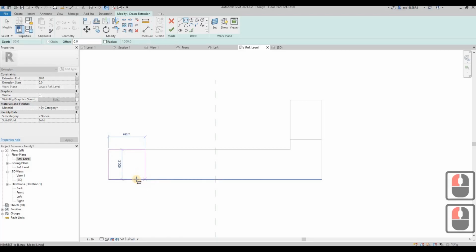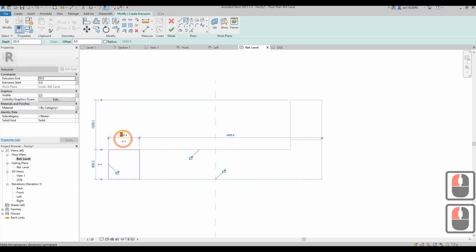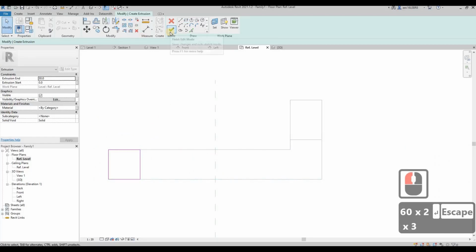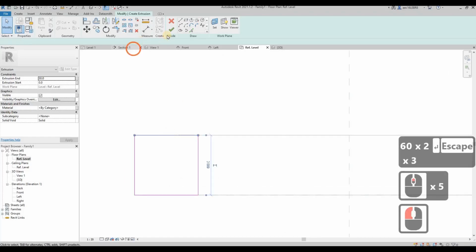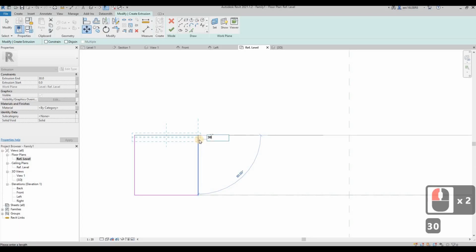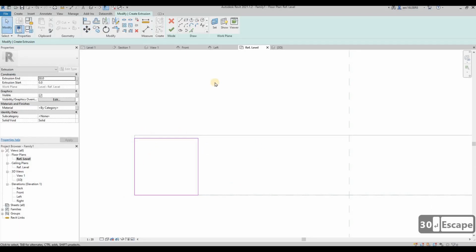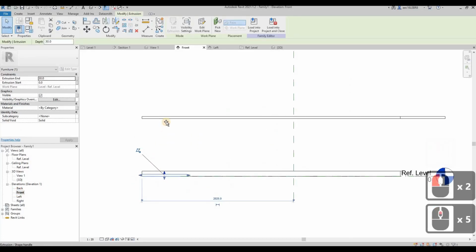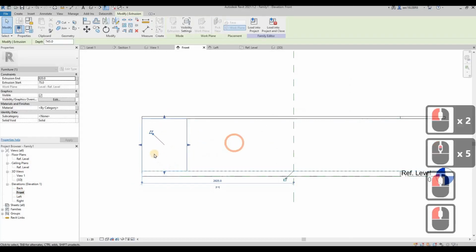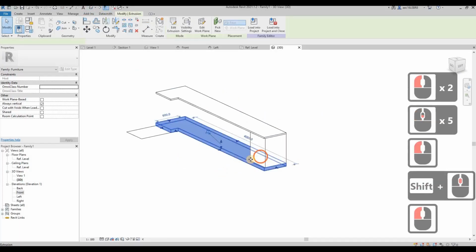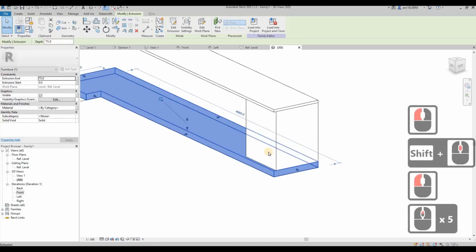So the standard size normally we are looking at is 600 mm. Okay, this is the first one. Then I'm going to recess a bit, about 30 mm, for my cover leaf. Okay, so click finish to finish our first extrusion. Then we raise it up to here. So this is my first carcass.